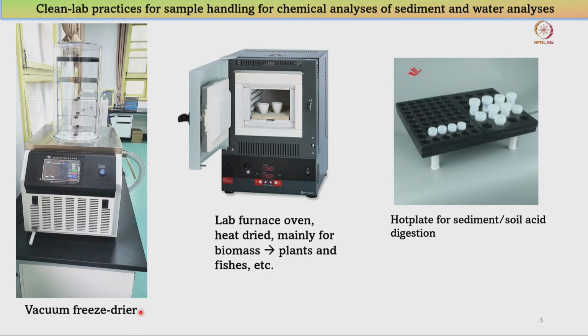What happens is that the sediment samples are frozen with a little bit of water, and then they are put into this freezer. This works on the principle that the water in the frozen state, that is in the ice state, will directly sublime. And what will remain is your powdery sediments. Now, those sediments will have to undergo digestion for analysis.